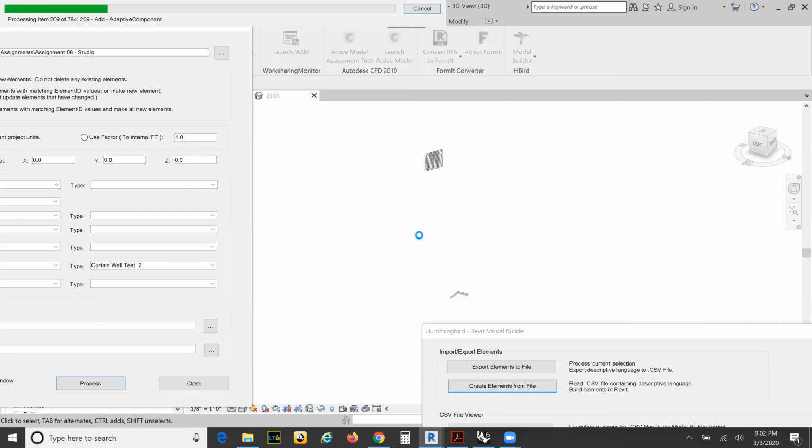We also had to have some true elevations to show to the city. So this is exactly how we put them into our Revit file. Again, all the structural engineering for the actual panels was through Grasshopper and Rhino, but the building itself was through Revit. So they had to make sure these talked.